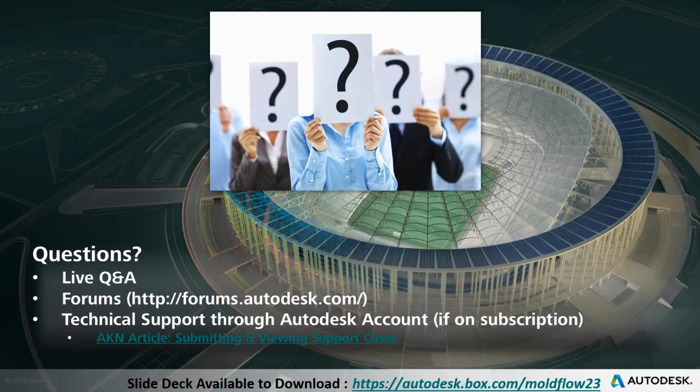But again, once you get into more complex geometry, that might not capture it the best. So you might ultimately have to turn to the 3D mesh to accurately get a good feel for it within the solvers. And that does circle back over to the material data as well. If you trust the material data for the midplane or dual domain analysis, then that could have an effect on swaying your answer one way versus another. But again, it might not be as clear-cut as you'd hoped. So, good question.